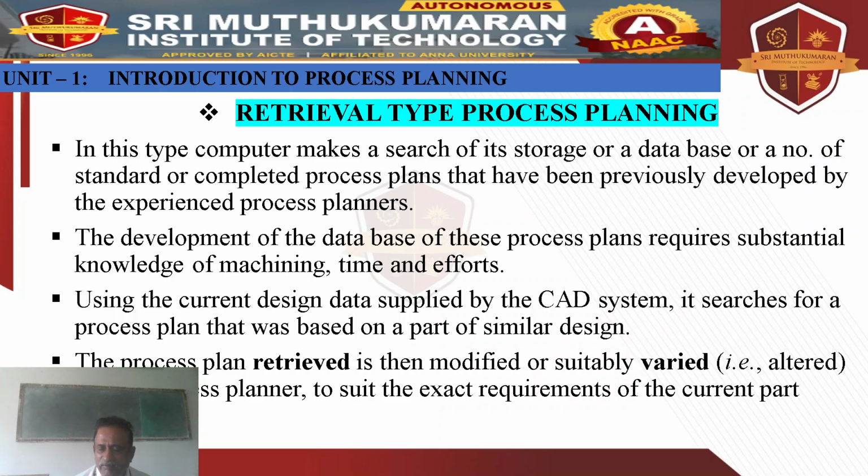So we have a database where there are plenty of process plans which are prepared by experienced process planners. This development of the database requires substantial knowledge of machining, and the time required involves more effort for the process plan. Using current data supplied by the CAD system, it searches for the process plan that is based on a part of similar design. So for similar components, we already have a process plan; this component is similar to that one, so we take that process plan, and this plan is retrieved and modified, that is edited suitably, to the current component to be produced.